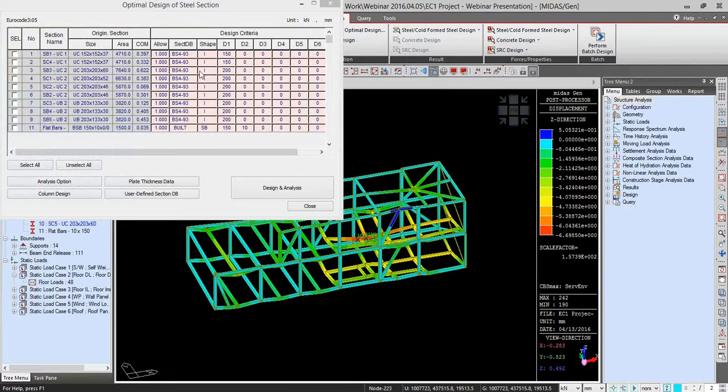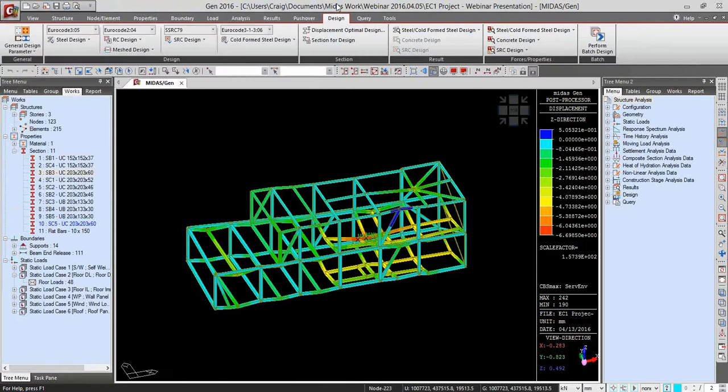So we did use this to help maintain our structures and find sizes that worked within our depth. So for a lot of our beams, we wanted to keep them to a minimum depth of 200 mil to maximize the floor to ceiling heights within the house, within the penthouse. So we used this function for that.